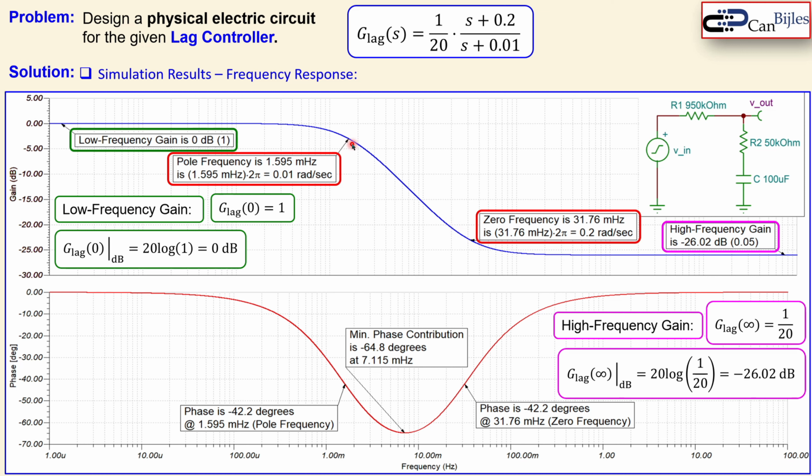Similar thing here, but then the reverse, you go up. We had here nothing actually in the low frequency part. Then the pole is dominating, and then the 0 is approaching, and then it cancels actually the effect of the pole. And then again, everything is the same as before, of course, then lowered in the gain. We also see the phase contribution is almost minus 65 degrees at max, as said before.